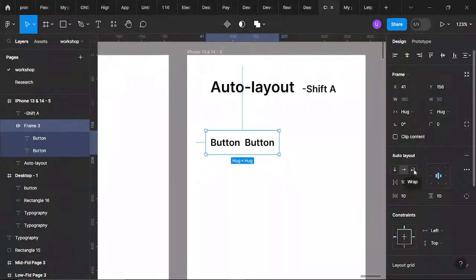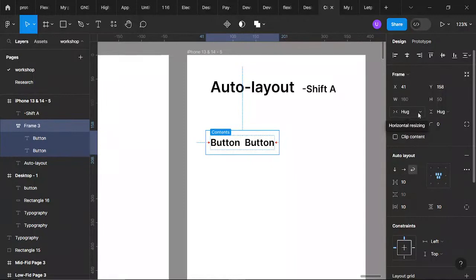So if you are using wrap, if you click on this wrap, nothing will happen yet. But if you go to org, I didn't explain that. On the width and the height, we have what is called org and fix. If you click on this org, that means that container should expand and contain everything inside it, irrespective of the width, irrespective of the height.